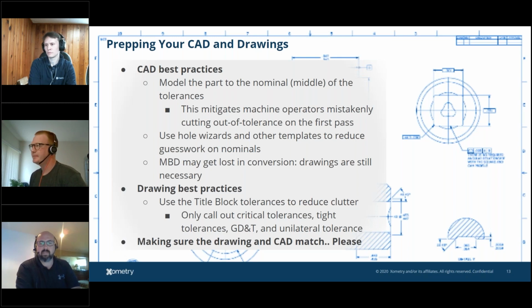Yeah, correct. Especially when you get into complex CNC mill parts, lathe parts. Sometimes you'll have a plus tolerance and a negative tolerance in the same part. And that becomes a problem with programming from the manufacturing standpoint, because some of the same tools are used to produce different features. So say you've got a feature that's got a minus and a feature that's got a plus. We can't just go in and use the machine settings to adjust those tools. We'd have to basically reprogram it, put different tool paths in. So best practice is just try to model nominally.